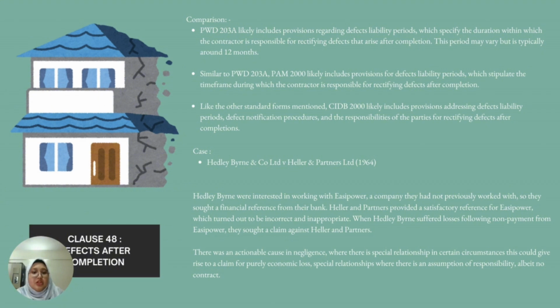Similar to PWD 203A, PAM 2000 likely includes provisions for defect liability periods, which stipulate the time frame during which the contractor is responsible for rectifying defects after completion. Like the other standard forms mentioned, CIDB 2000 likely includes provisions addressing defect liability periods, defect notification procedures, and the responsibilities of the parties for rectifying defects after completion.